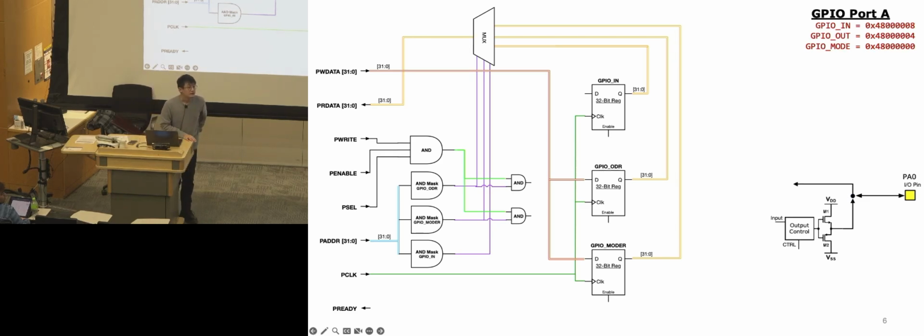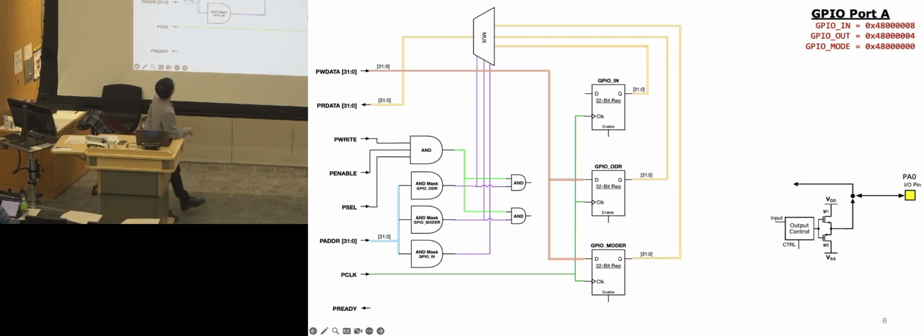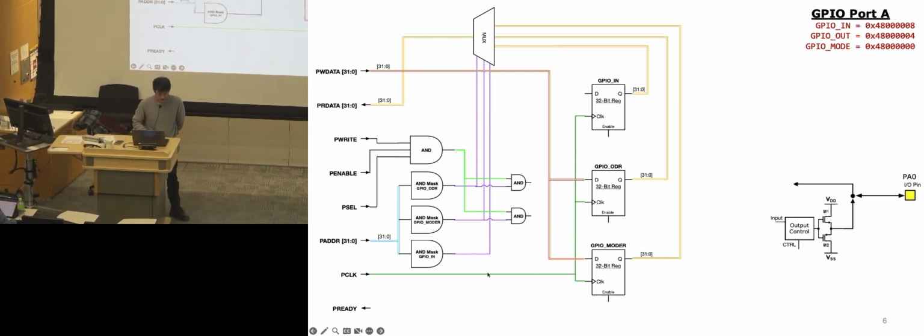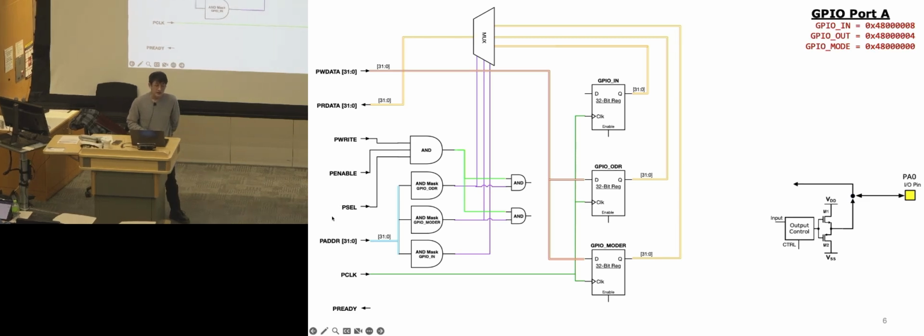Yeah. So wait, you said the p-address selects registers within a single peripheral. What does the p-select do? It selects each peripheral? Yeah, the p-select pin is an individual signal to each peripheral to tell whether this peripheral should be the one that responds. And then inside this peripheral, there are multiple registers that could be called or activated, and that is decided by the address.